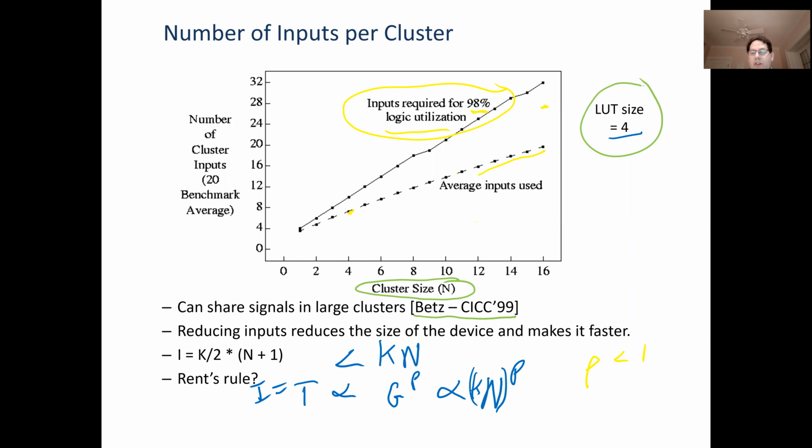So at 98% logic utilization, it means most of your logic blocks are packed all the way to be full. Does that make sense? Yeah, but if the curve for 96% was here, and I just drew that line in, then the area savings between these two curves might pay for adding 2% more logic to the chip.